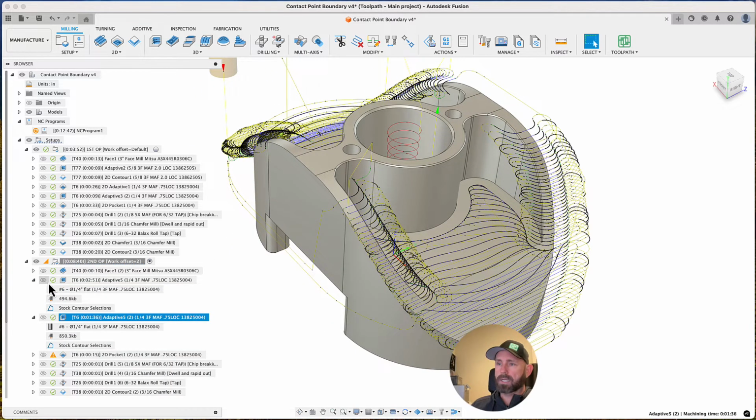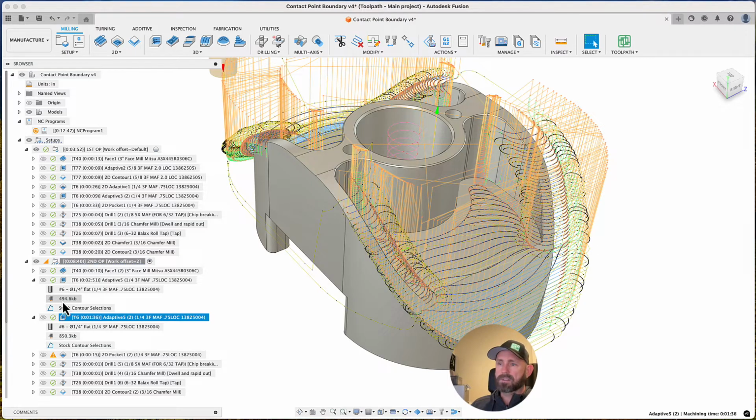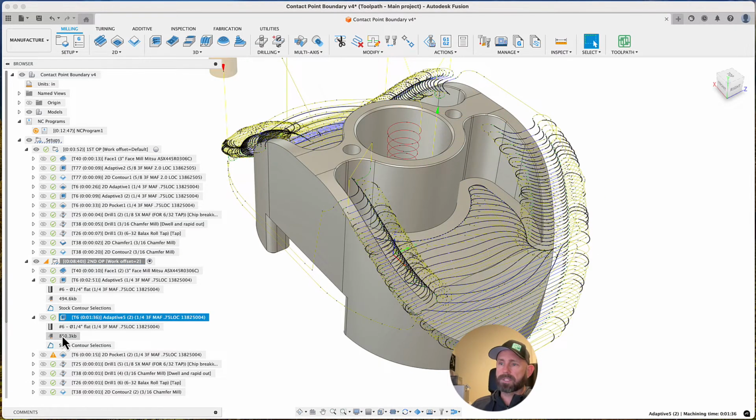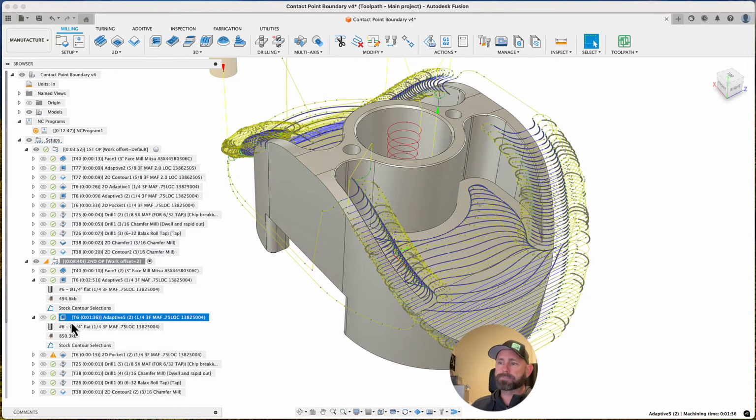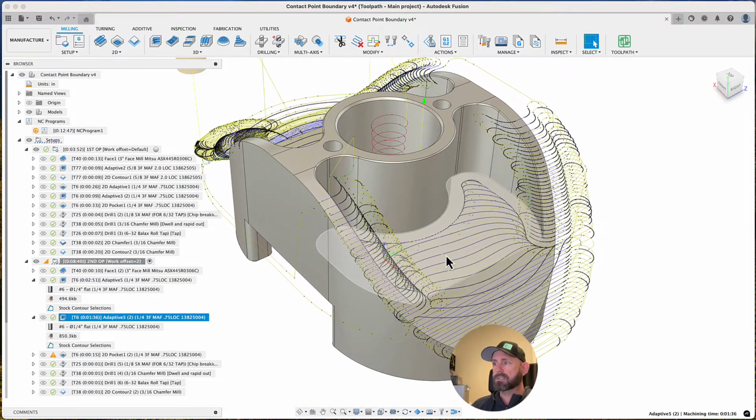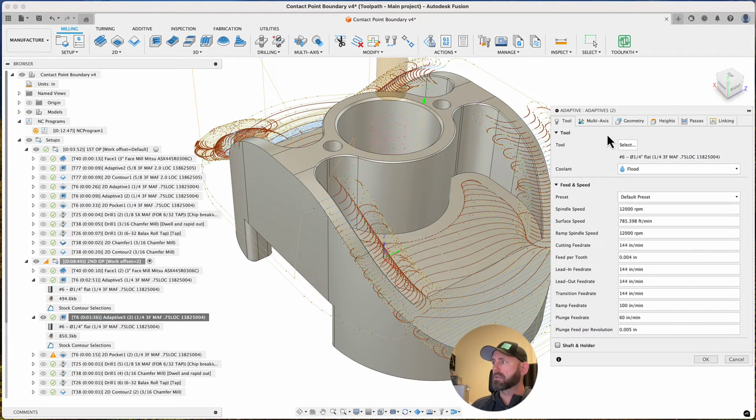The other thing to look at is when I expand the toolpaths, this is almost 500 kilobytes, this is 850 kilobytes. This isn't a one-to-one exact replica of how big your G-code program is going to be, but it's actually pretty close. If you cut this to be half of that, the code ends up being pretty similar in how many lines of code. So depending on the machine you have, some machines like tons and tons of code. So maybe this is a better program and you'll actually get better machine motion with all this code. The Haas that I have out in the garage is the opposite.